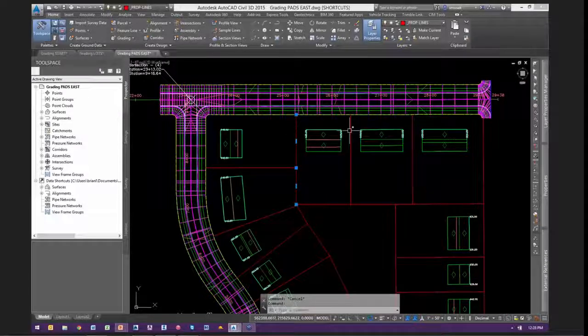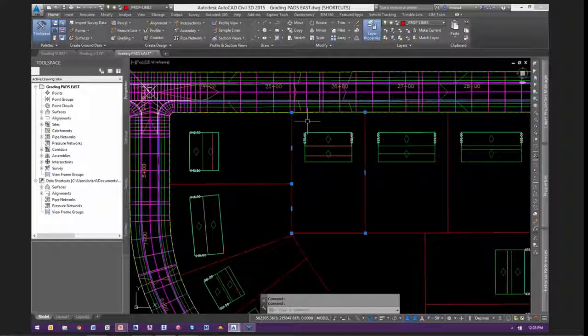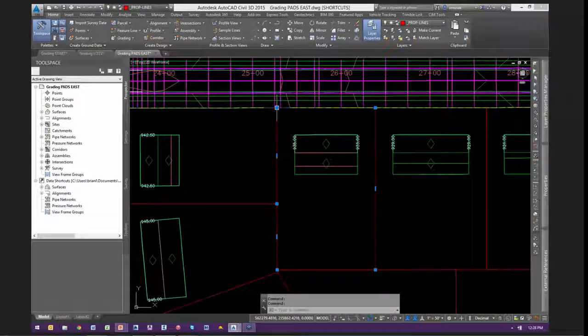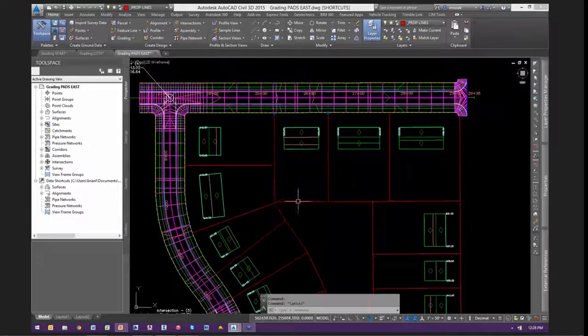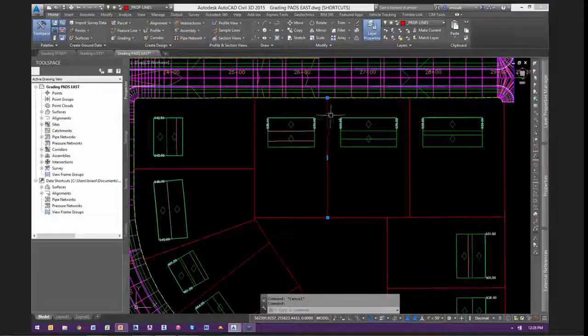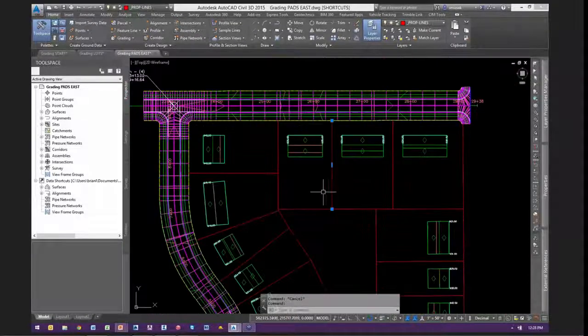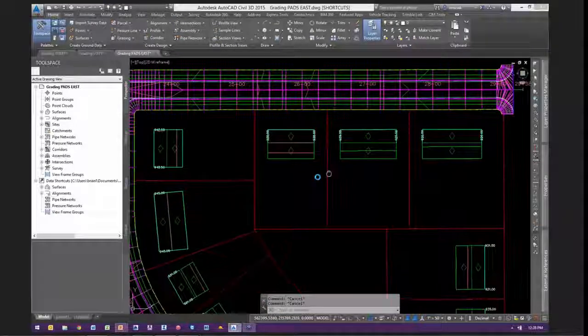So the fronts of these feature lines tie right into right-of-way. How can we assign elevations right there? We can pull elevations from the corridor surface. Then what about the back of the lots? Well, if we pull elevations from corridor surface, I can then use quick elevation edit to do some typical slopes draining back to the pond. That will go right here, so 5–10% grades back. So here's what that'll kind of look like.